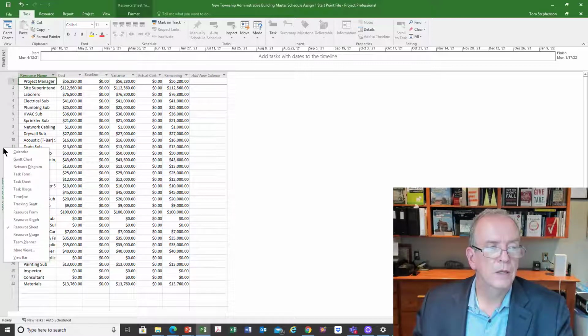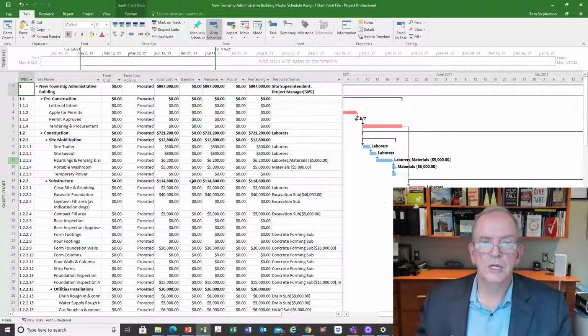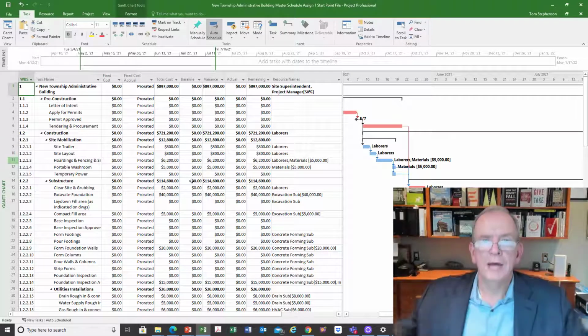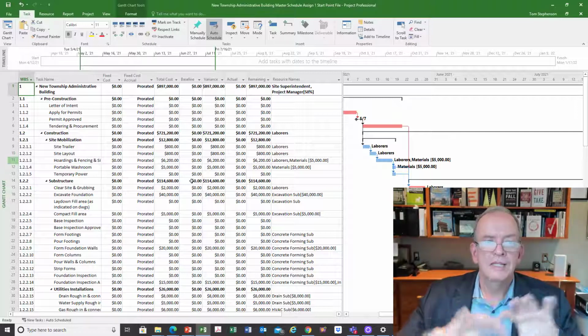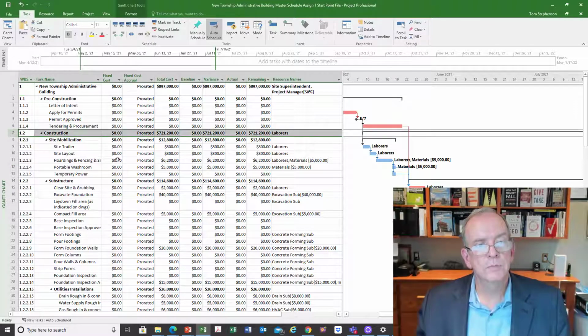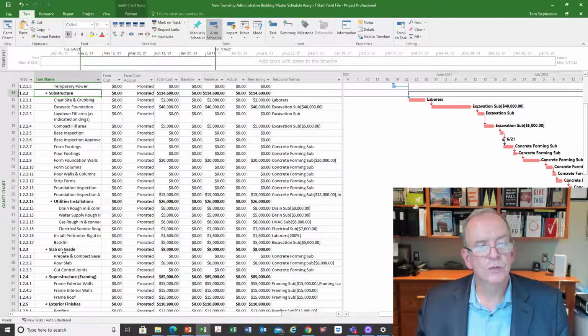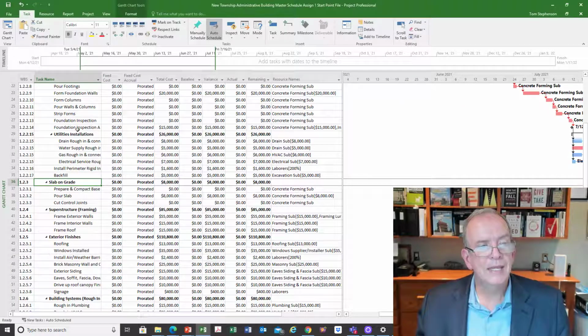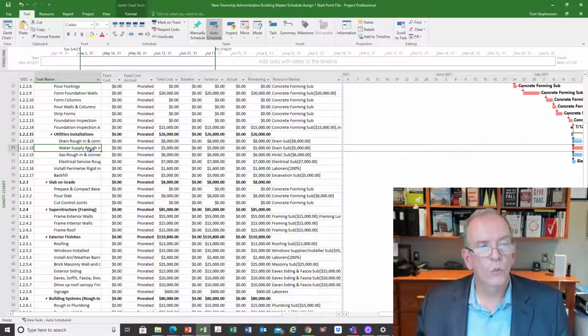So if I start with the construction documents, and I have the engineering drawings, the structural drawings, the specifications, and beyond that, the other drawings that I mentioned, landscape drawings, mechanical building systems, I start to separate the work into smaller components. Like at the beginning, it's like, wow, this is this big thing. And if I can start to separate it out, we call this a work breakdown structure, into areas of work, I can keep breaking it down further and further if I need to, so that I can figure out what I need to do.